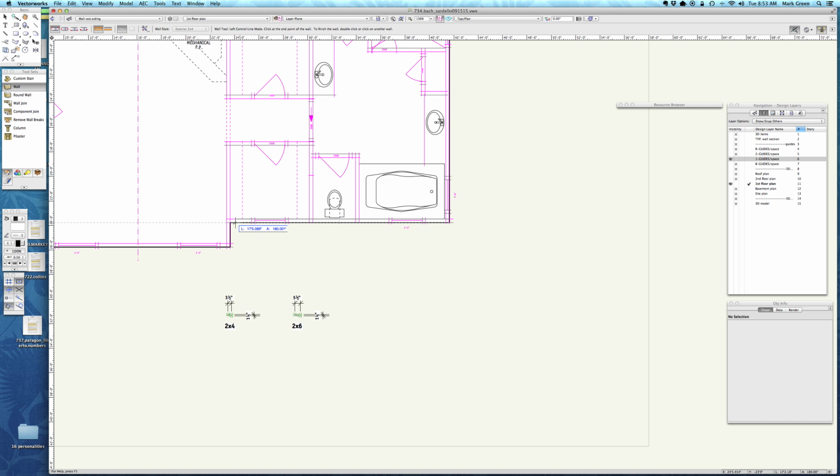So if I'm drawing at a 90-degree angle, that's where I want. All these walls are going to be, unless you got a 45 in there somewhere. All of these walls on this house are going to be at a 90-degree angle. So just keep the shift key down the whole time. Go over here. You can either hear or see that it's clicking right at that point. Going down, it's clicking at that point.